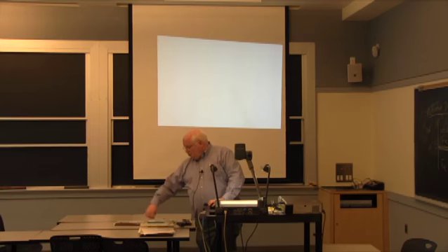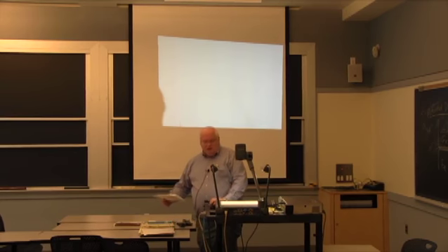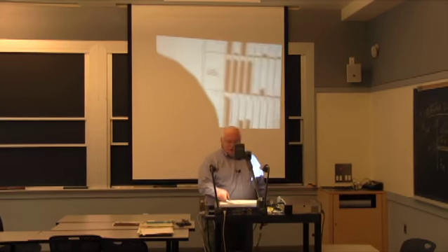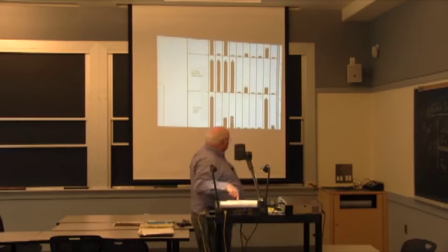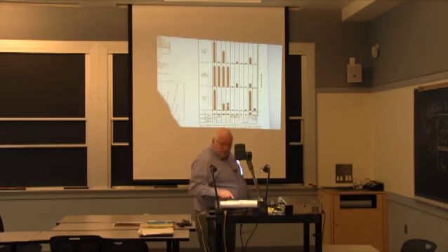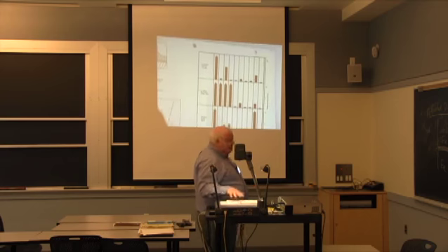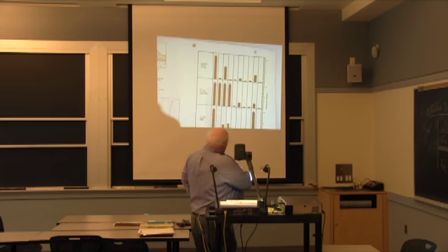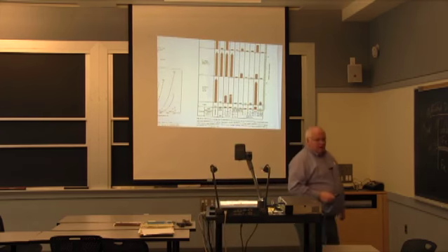Okay, in the real world of soldering, though, it turns out that the kinetics of cleaning are such that it controls most of our soldering operations. And this comes out of an old soldering manual from the 60s, where we don't have to blow it up so you can see it a little bit better. We don't have to see everything. This is what they're looking at here: 6 months old, 21 days old, 24 hours in steam, and a freshly cleaned copper surface. Okay?